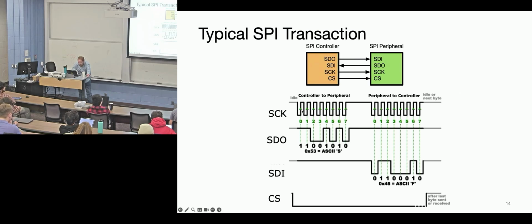So here, we're just indicating, can you see my cursor? Yeah. We're going to sample at this edge, and we're going to look here and say, oh, this SDO is high, so it's a logical 1. Then you transition. In this particular case it was 1 again, so that gets toggled high, and then it gets sampled in on that rising edge. Here the data is going to change, this is the setup phase, or the toggle phase, and here the data is changed. The data needs to stabilize, and then on the rising edge, it gets clocked in. Okay. Great.